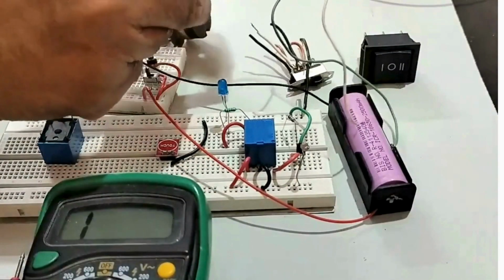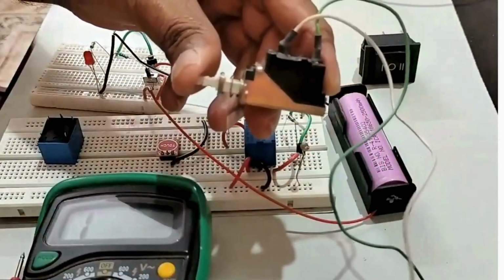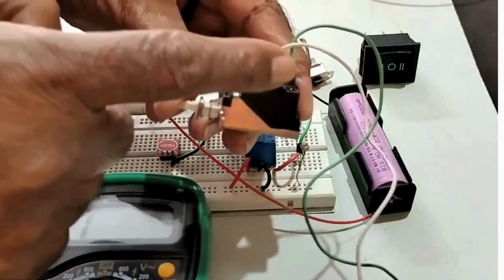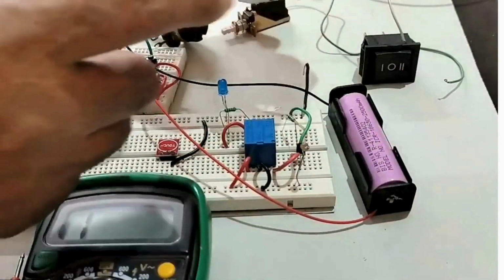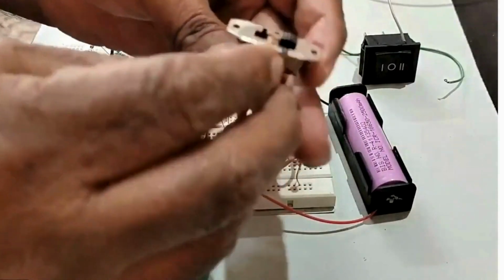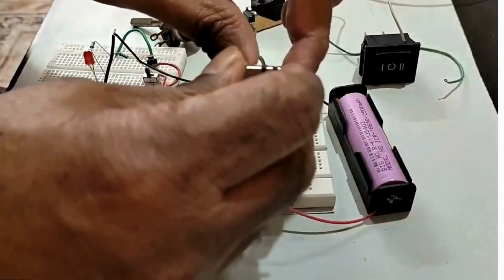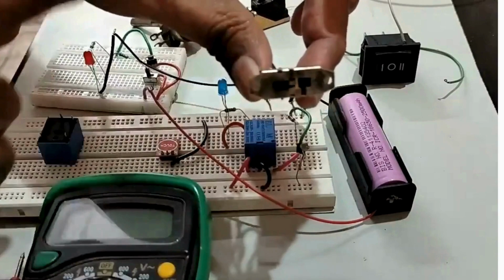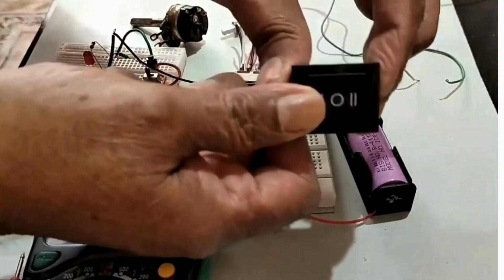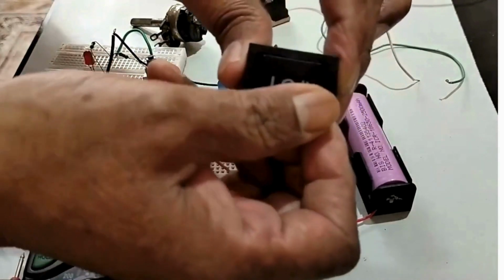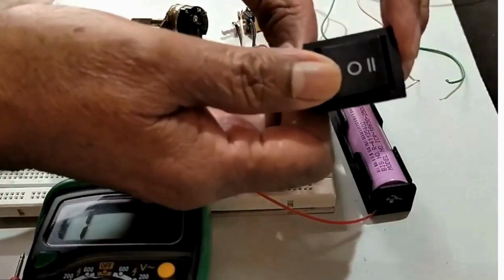This is a push type on-off switch, a very common type that we use for televisions and AC switches, on and off. Single pole, single throw, only 2 connections. On, then off. This is a slide switch. It has 3 positions, and the center is off. One side connects to one pole, and the other side connects to another pole. These are switches which regain their position. If you press it, it returns to position. This is for video games, so we call it a joystick type switch.